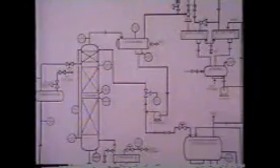This reflux is necessary to start the vapor-liquid contact in the column. However, when the column is operating normally, it produces more overhead product than is necessary for reflux. This excess overhead collects in the condenser leg. A level controller monitors the level of liquid in the leg. When that level reaches a predetermined point, the controller opens the overhead product recovery valve, which allows a portion of the excess liquid to flow to the overhead product recovery tank.